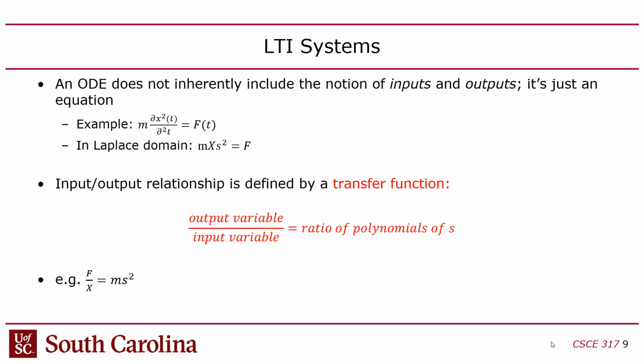But a transfer function is when you take that equation and restructure it into a canonical form where it ends up being a ratio. I think it's always a ratio. All the ones I've seen are a ratio between the output variable over the input variable. So in other words, a transfer function introduces this concept of an input and an output into a differential equation. Ultimately it's just an algebraic restructuring of a differential equation.